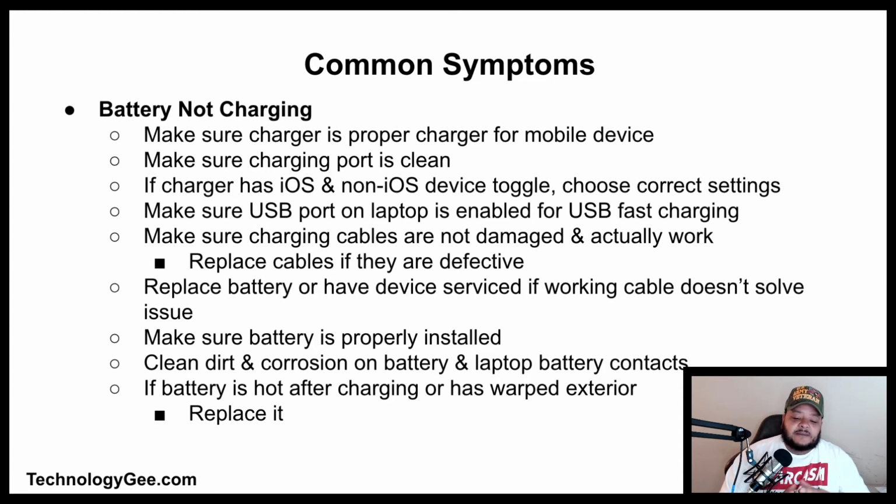You also need to check to make sure your charging cables are not damaged and actually work. If they don't work, you need to replace the cables, replace the battery, or have the device serviced. If a working cable does not solve the issue, you need to make sure that the battery is properly installed. You need to clean dirt and corrosion from the battery and laptop battery contacts. And if the battery is hot after being charged or has a warped exterior, you need to replace it.